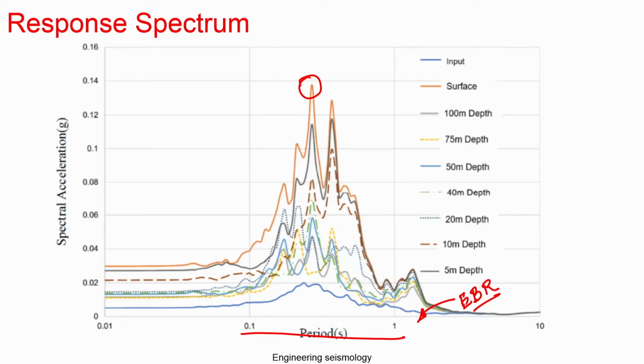Okay. So, you can see there is a variation. This is how you can get a response spectrum by doing a response spectrum analysis. So, you can take time history data and solve the wave propagation equation using a single degree of freedom system, and you can get the response, typically the response at different depths. The time history will give you the total clear picture of your particular earthquake.